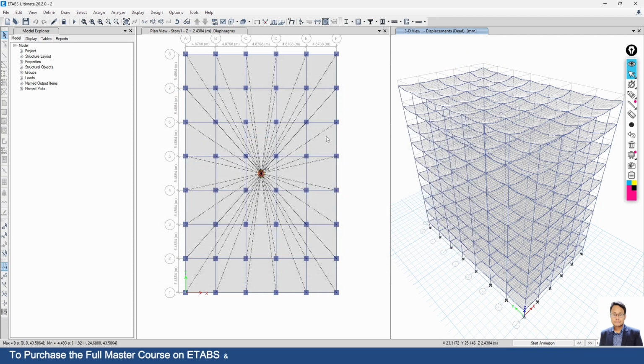Okay, basically we check this buckling effect when we are designing residential cum commercial buildings, because for the commercial floors we have to assign more height than the residential floors. In that case, definitely I will recommend to check the buckling effects.